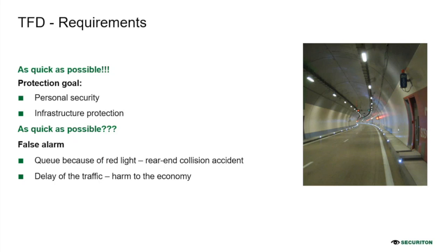Another thing is, due to a false alarm you may have a delay of the traffic, which is not very interesting, especially in the rush hour when everybody's going to work. Then it's also a waste of energy, because usually, depending on the concept, you shut down the ventilation system, and then you have to switch on all these generators again. This is quite a big waste of energy if we consider that a long tunnel has many such ventilators. This must also be considered a disadvantage of a false alarm.